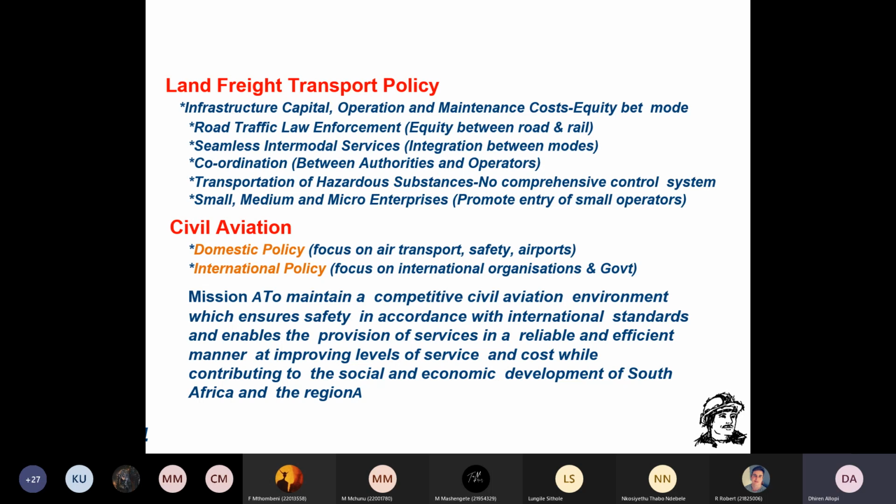E80s is your 80 kilonewton axle load on your road. So if your road was accommodating certain amounts of E80s within a certain class, it could last a lifetime. But the moment you bring your heavies onto your roads, high number of E80s, certainly your roads will not last, and therefore you need to maintain your roads regularly.